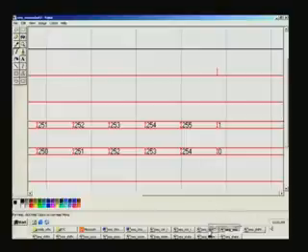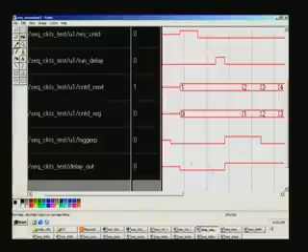In the earlier case we saw that this delay out is going high here and remains high till it was 254, but this is corresponding to this 0 here, 0 itself is spread over a 1 clock pulse. So in other words, last one was 254 plus 0, if you add, you have got 255 clock cycles delay, that is what you have got.